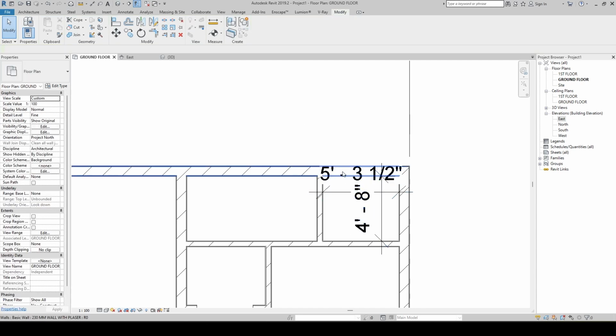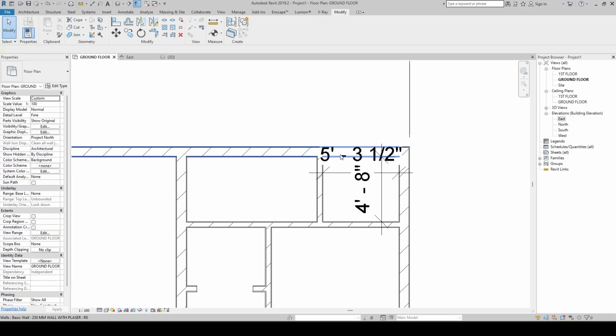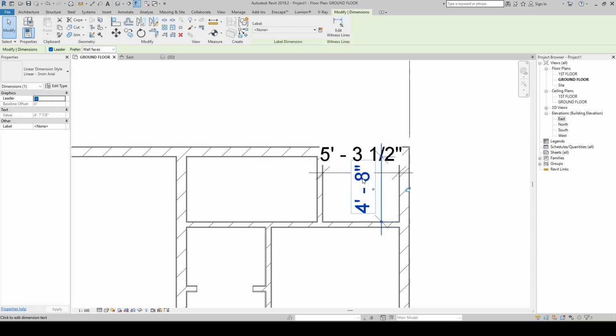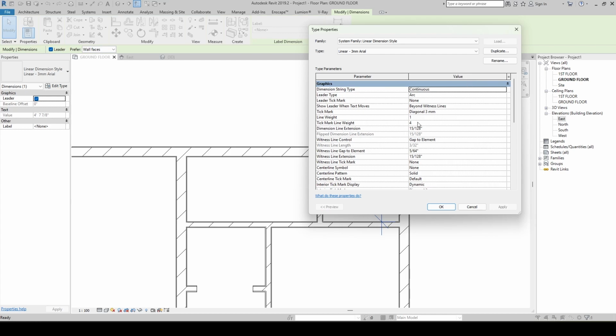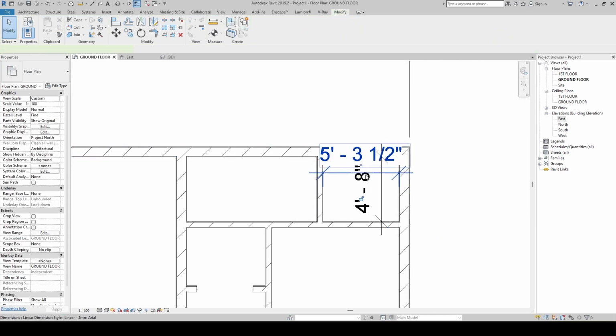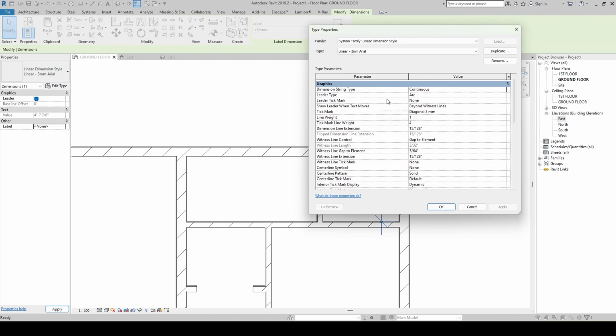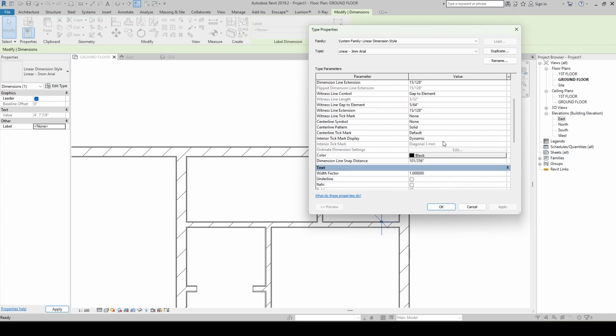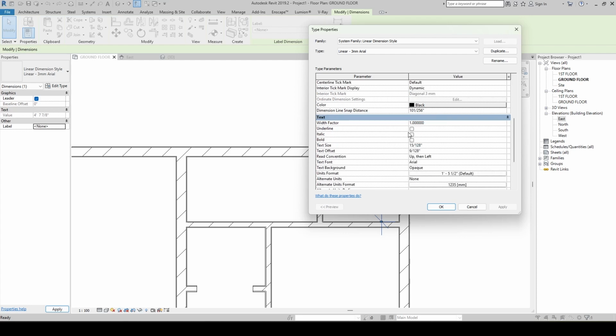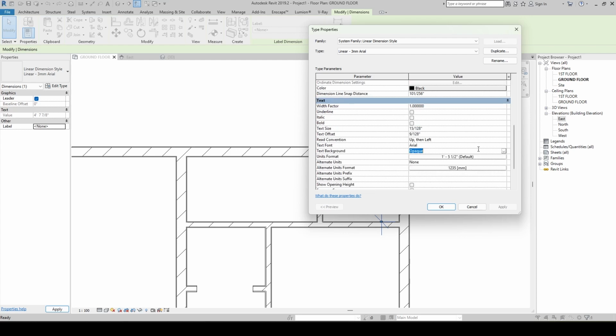Maybe as of now, in order to make it transparent, I'll show you one small thing. As of now the wall is not showing behind this text. To enable this, let me select the text here and go to Edit Type, then the leader mark, leader thickness, and go to the element text, the text line pattern, center line. And the text, yeah, you will find the text background. As of now, select it as opaque.